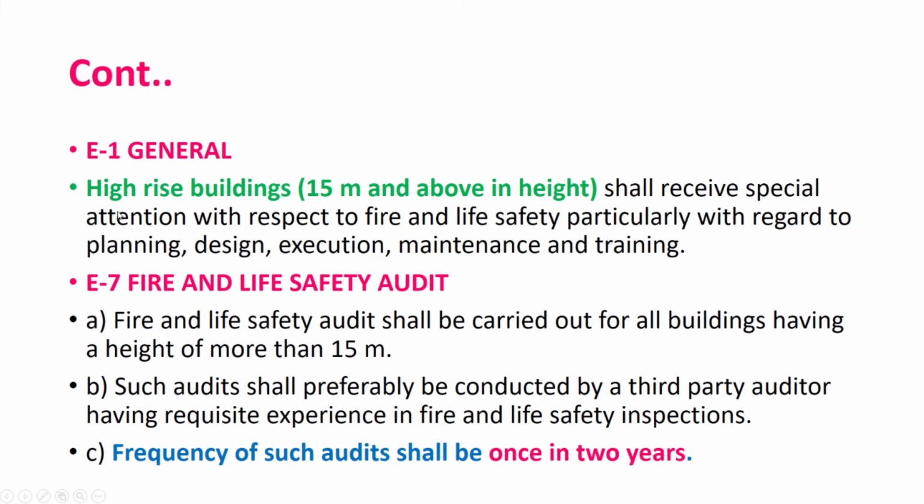This is again with respect to the water supply and drainage plan. Suppose, due to any reason, there is flooding in the room itself, and how the water will go outside. So again they have specified a certain slope of 1 in 150 in the room itself where the spouts are there. But many times we don't provide this, maybe in certain areas where there is a lot of possibility of having water near the location of the septic tank.